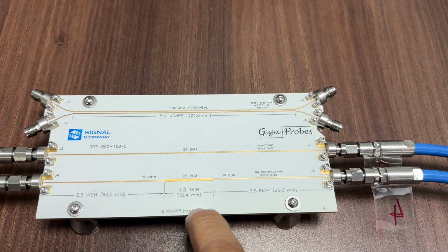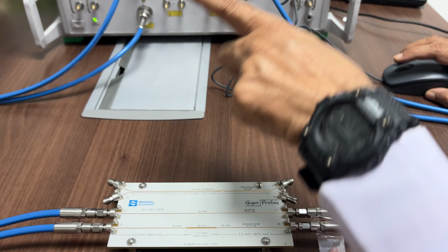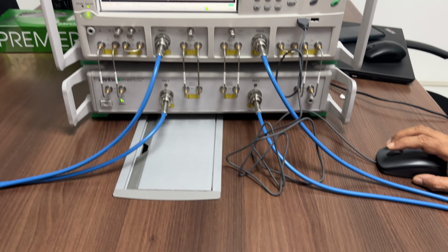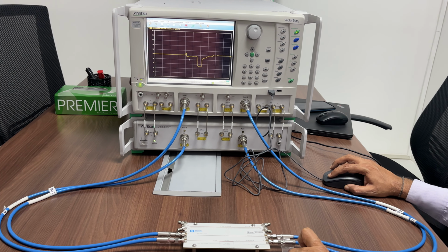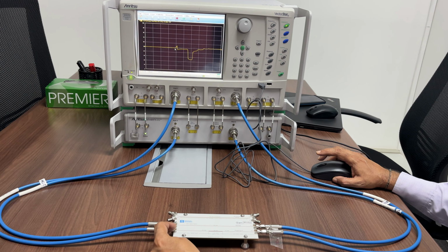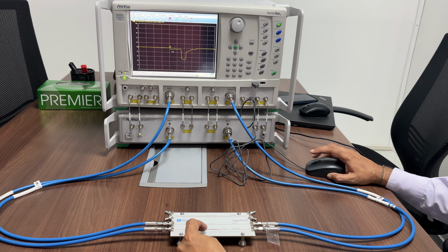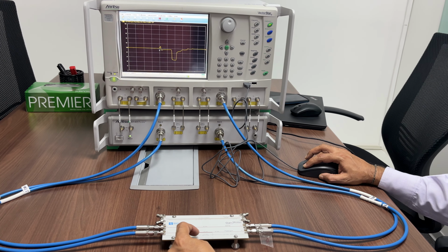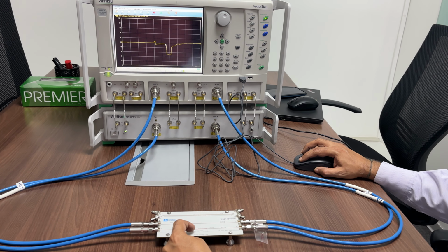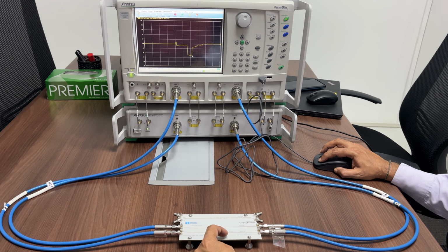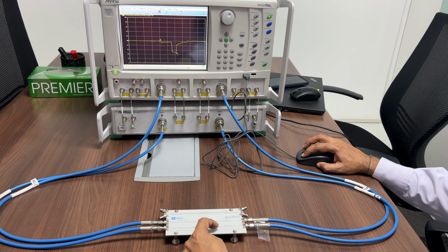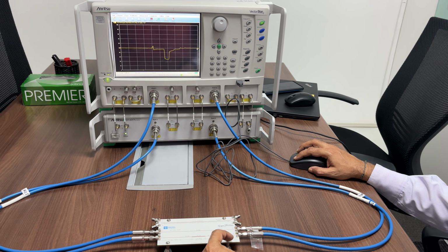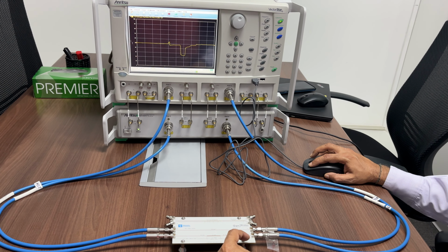If you want to see this in the time domain, here we have connected the third port. In the S33 we can see that there is a transition here because of the signal, and then we have a path. This path is the 50 ohm path. After that there is a sudden dip, like a 25 ohm path. The signal has gone down to 25, and then again it will go back to 50 ohms. So this is how we can see it in the time domain.